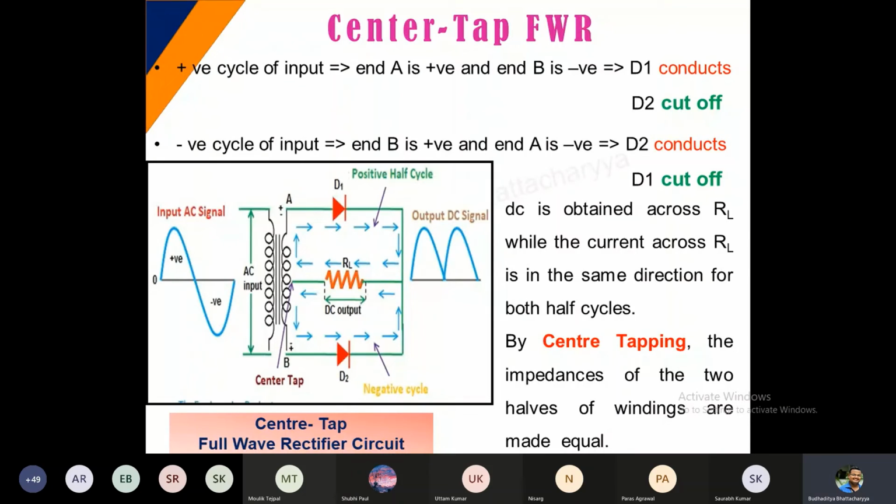Half wave rectification, all of you have understood, I guess, that whenever we have a diode and the diode is supplied with an AC supply, based on the positive and the negative half, ideally the diode will act as forward biased or reverse biased. When there is a forward bias, it will allow the output to happen. When it is reverse bias, it won't allow it.